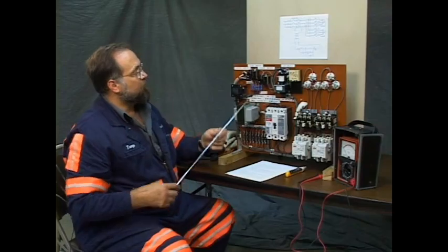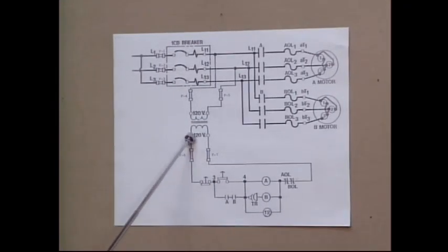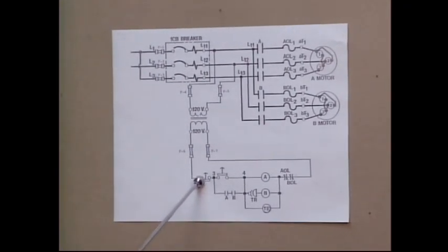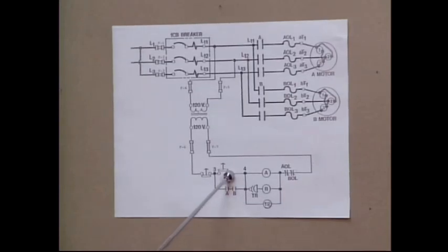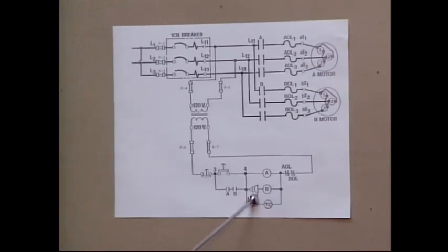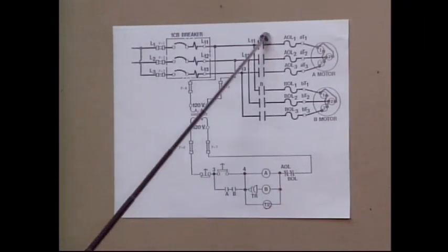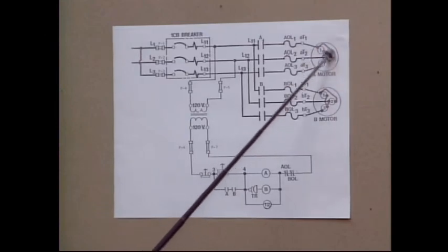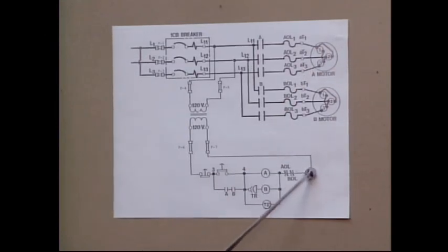Okay. When you depress this start switch, you're connecting the one side of the transformer, X1, through the start switch. When it's depressed, it goes directly to A coil. It also goes to the line side of the TR mercury tube and to the line side of the TR coil. Well, after A picks up, it closes these contacts, allows power to go to these bulbs. They come on. You have a circuit. And then B should come on.